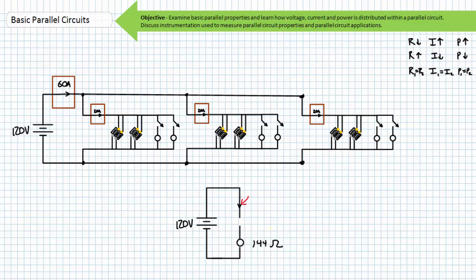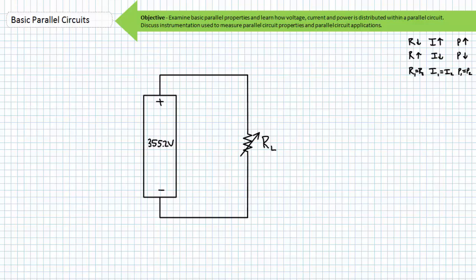Electrical loads typically aren't wired in this fashion. Ideally, every electrical load designed to run on 120 volts receives 120 volts because they're all wired in parallel with one another. You can think of each load as a rung in a ladder, one load and one load only per rung. We'll return to this topic when we discuss ladder logic diagrams, a common method of schematic drawing utilized in motor controls. Now let's consider not electrical loads in parallel with one another, but rather electrical sources in parallel.